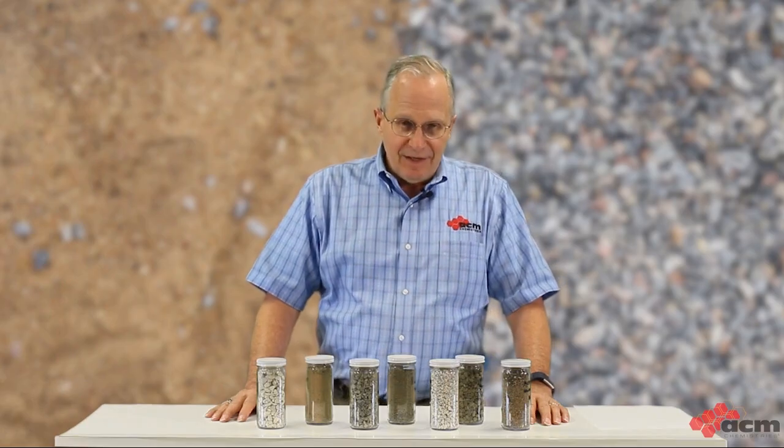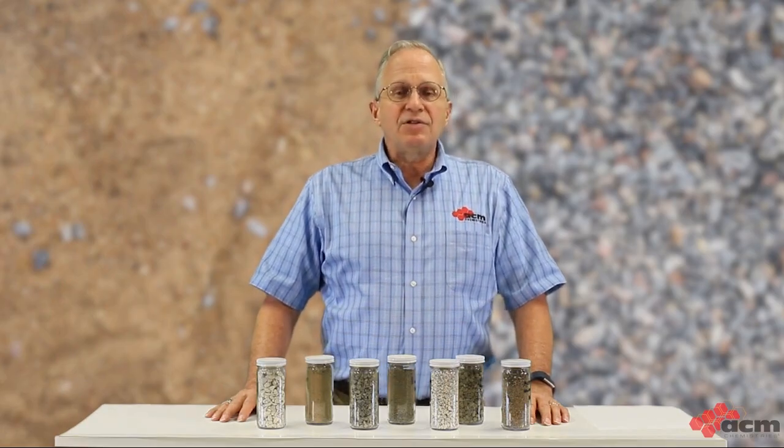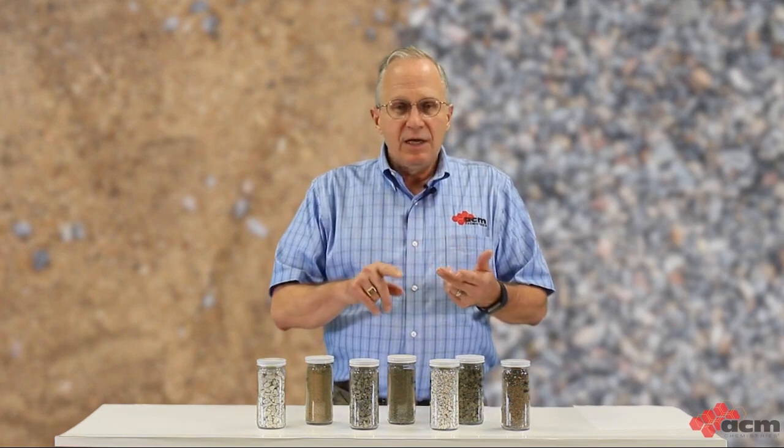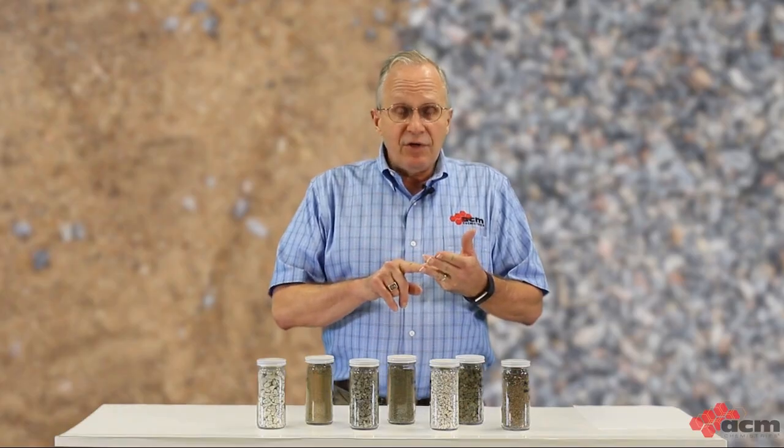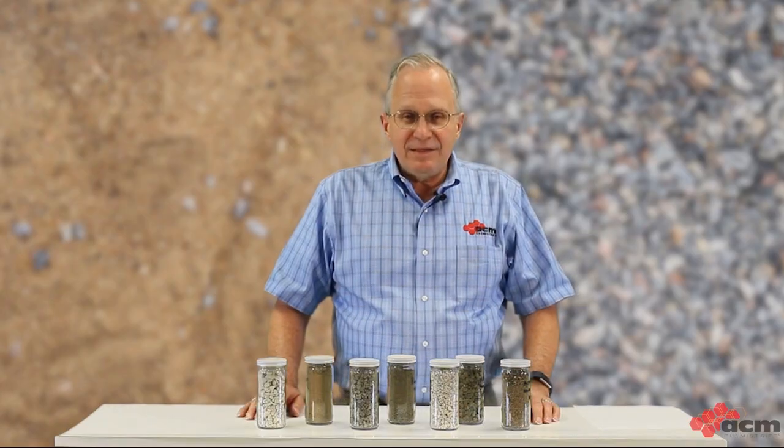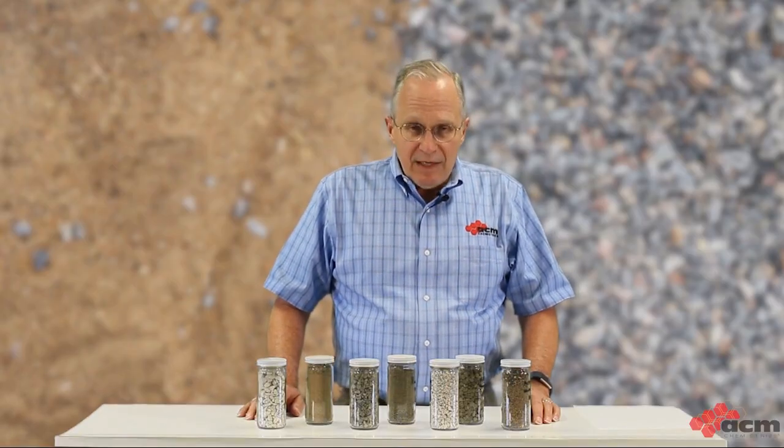So let's review what we've learned today. Aggregates are very important because they're the largest component of our concrete mix and affect everything from appearance to performance and the cost of our units. Size, shape, and texture matter, as well as particle size distribution or grading. If we get optimum grading by combining 2 or more aggregates so that it fits our target curve, we can achieve maximum density and improve performance at the lowest cost.